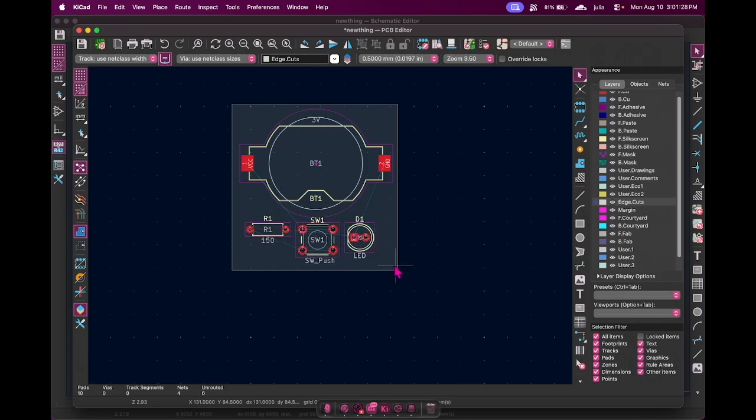Oh, I should have mentioned this. I forgot to mention it earlier. But you guys are new to KiCad, so you probably haven't noticed this yet, but if you want to select a component, you have to drag from the bottom right to be able to select the actual entire thing. Like if you try to select from the top left or something, it doesn't... Sorry, I lost my train of thought.